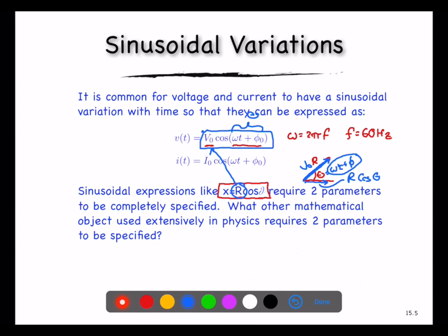And because that angle is time dependent, this vector is going to rotate around, tracing out a circle. And as it goes around this circle, the function that we're representing, the voltage, is just the x component of this. So it's the projection onto the x-axis of the tip of our vector. And as the vector goes around, that point is going to go back and forth and back and forth, sinusoidally oscillating, just as our functional form would have us represent.